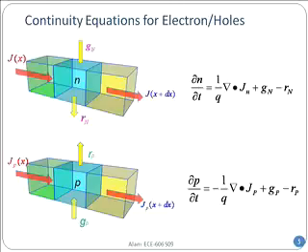The only thing that is different in the second equation is, do you see this? There is a negative sign in the first equation. And why is there a negative sign? Because holes carry a positive q. So when you write the equation, in the denominator you will write a plus q. And once you do everything else, because of that plus q in that term, you will have a correspondingly negative of the divergence. That's it. And so therefore, these two equations will be globally linked.